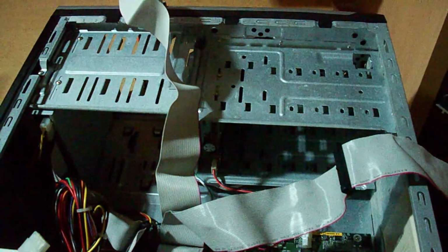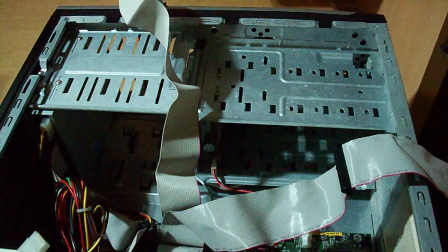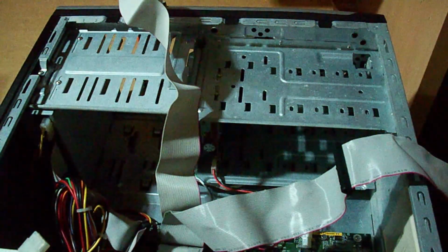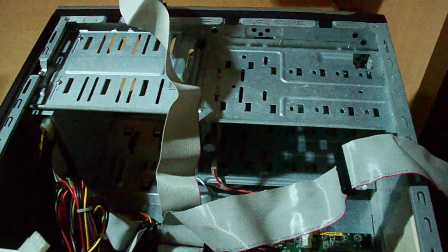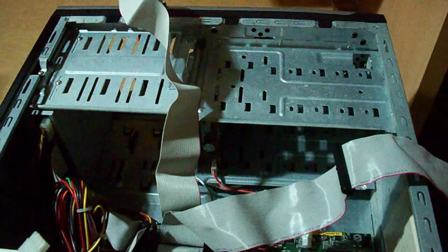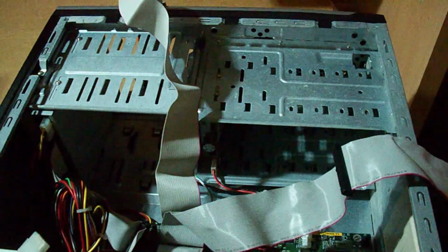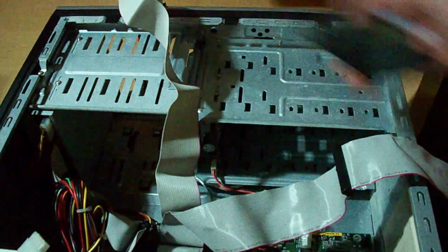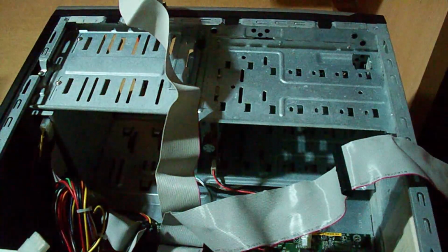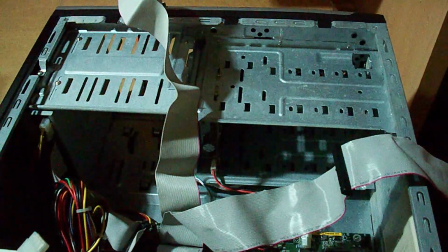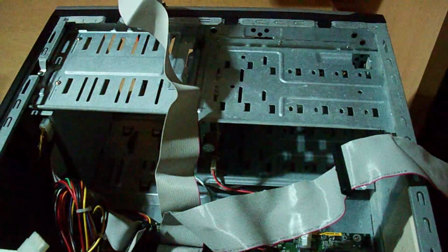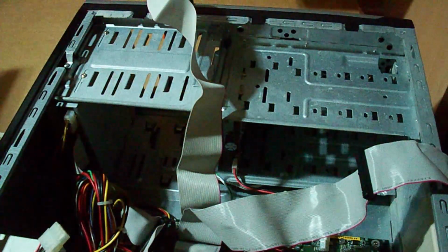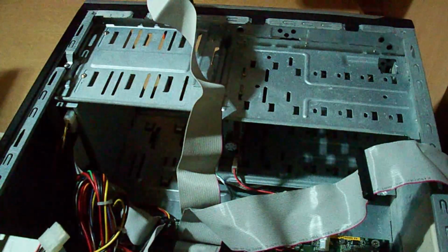These SD adapters have this small problem with the contacts being all uncovered. So when placing them on your machine, you have to be careful so you don't short the board. I'm going to attach it to this part of the chassis, taking advantage of those holes on it and using supports similar to the ones used to attach boards to the chassis itself.